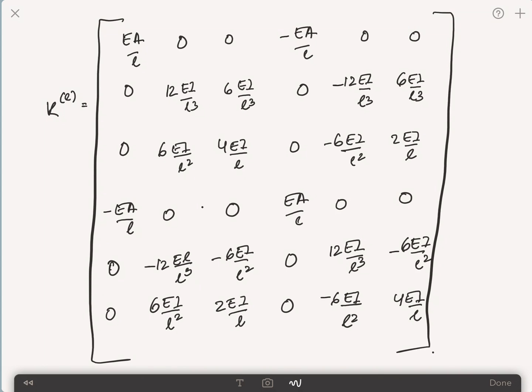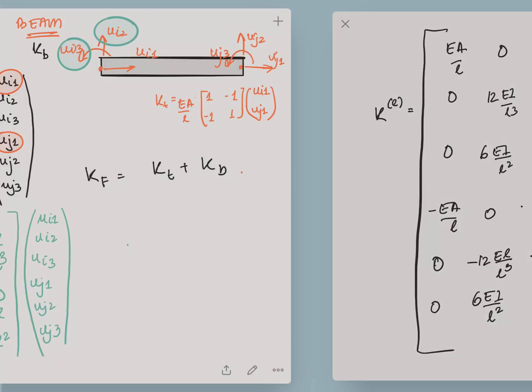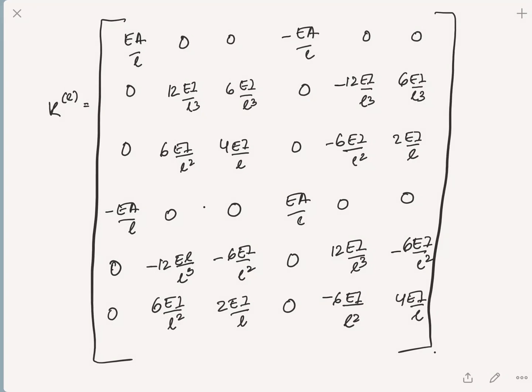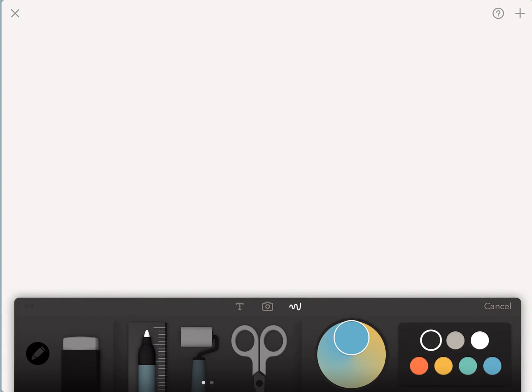Now of course this is for any beam element which is always lying in the global coordinate frame. Now, as we've already covered transformation, I'm not going to do that in details, but if I know the transformation matrix for any element, then I should be able to find out the global element stiffness matrix by multiplying T transpose K T, where T is the transformation matrix.